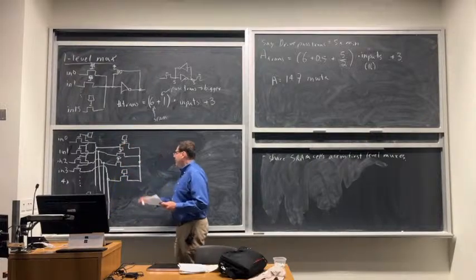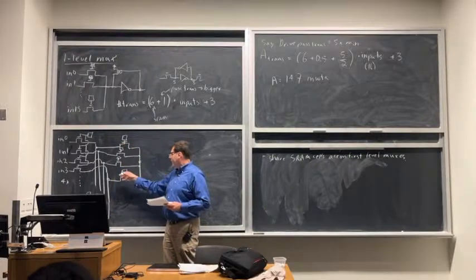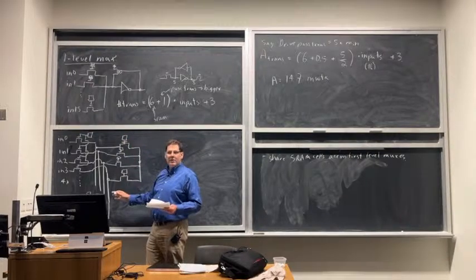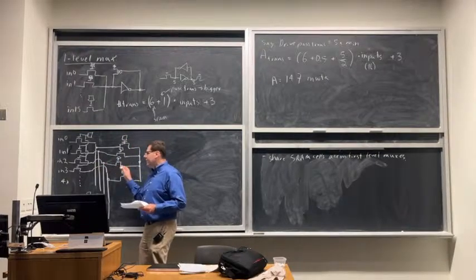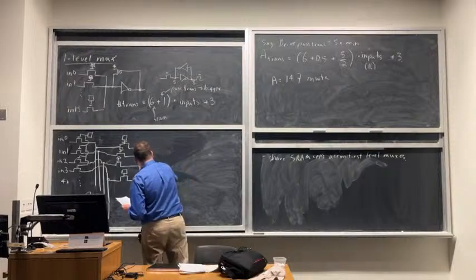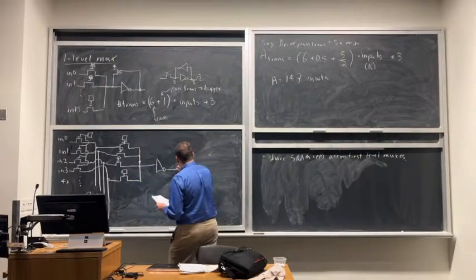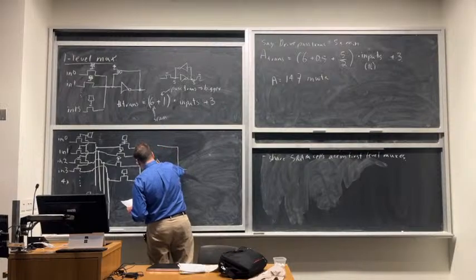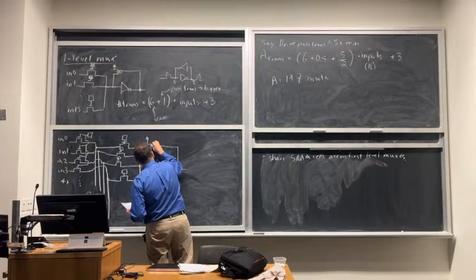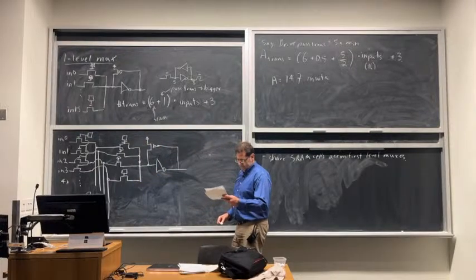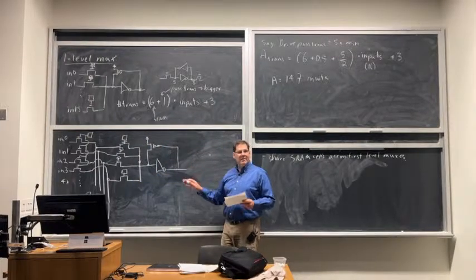Okay, so this is my second 4-to-1 mux, which is a regular 1-level pass transistor mux, right? I turn on exactly one of these signals. It's going to pull one of these 4 intermediate signals out to the output, and then I have my standard inverter to make sure I isolate downstream capacitance, and this weak pull-up to make sure I pass a logic 1 properly. Okay, so everybody understand how it works?